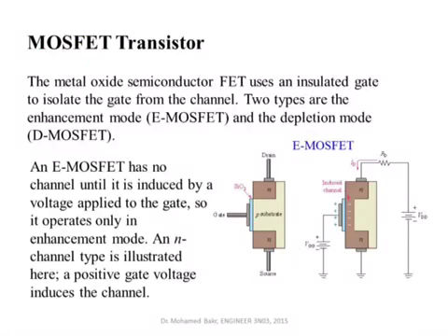There's an insulator here. So if I apply a positive voltage on the gate relative to the source, I'm actually attracting electrons to accumulate near the surface of this capacitor here. And this creates a channel of high concentration of electrons, and these electrons can drift against the applied external electric field to cause current to flow. So current will be flowing in this direction, from the positive electrode of the battery to the negative electrode of the battery, and the electrons are actually drifting in the opposite direction.